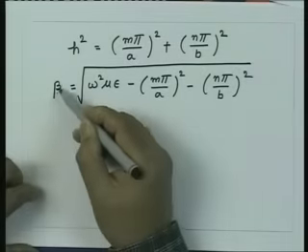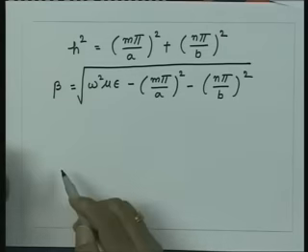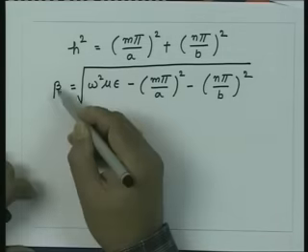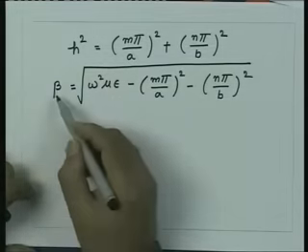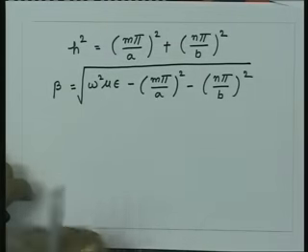In parallel plane waveguide, we had called this quantity beta bar. However, in this case, since the net wave propagation is going to be in the z direction, just for simplicity we have dropped the bar, but beta essentially means the phase constant in the z direction, or along the waveguide.